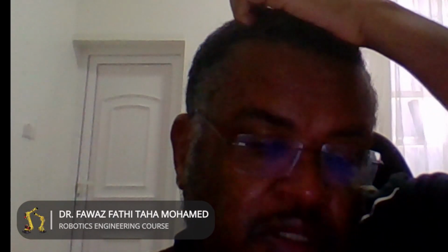x, y, z, 0, 0, 0, and 1 is used as a temporary number for the homogeneous transformation. So I have here the 0, 0 in the new frame, represented by this homogeneous vector. I want to find this point with respect to the world frame.